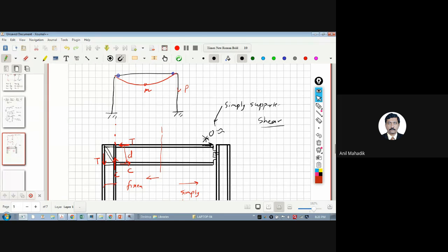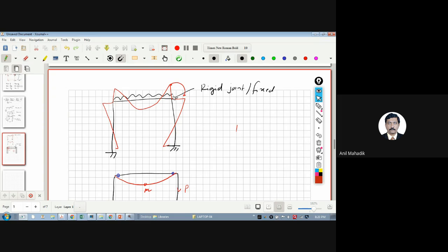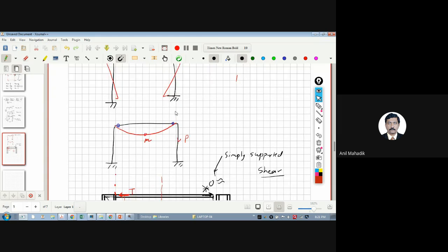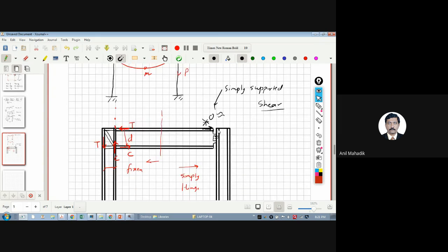Right? Yes, sir. This way we can handle. So Staad doesn't understand what connection you are designing. You have to decide that I want this rigid joint. Then we can tell the Staad, please analyze this. As an engineer, if you feel I want this hinge joint, then tell the Staad, release the start and end, give me the forces and moments. I will design it and I will detail like this.